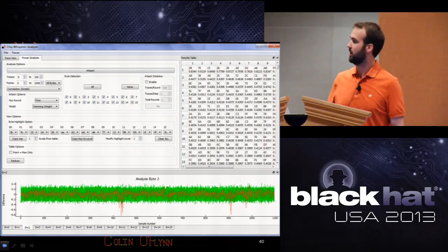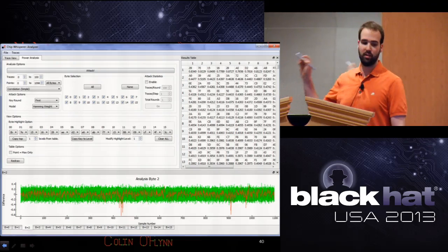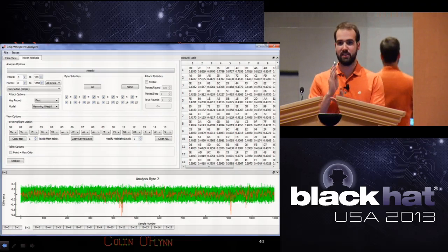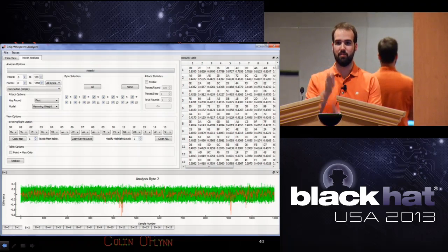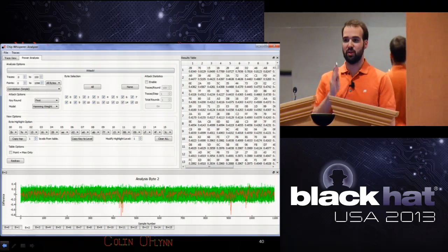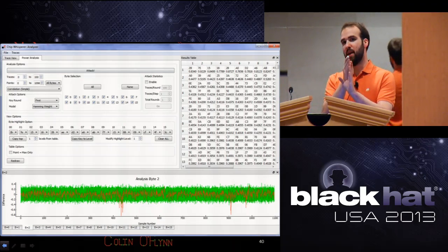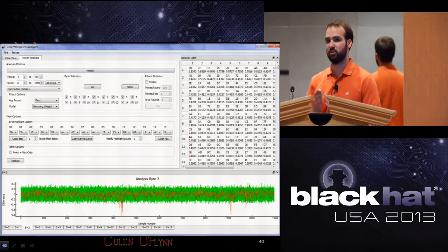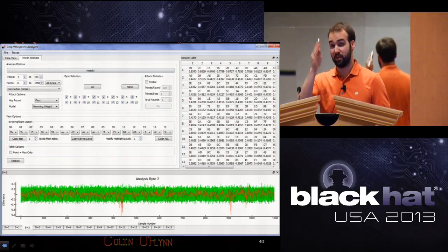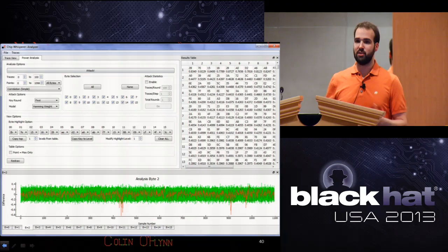On my system, I start the recording for the testing right when the device puts a clock line high that says I am now doing encryption. So it's perfectly synchronized. I know, from that point there is X cycles before the encryption. So they all line up. They do have to line up. If they don't, it won't work.